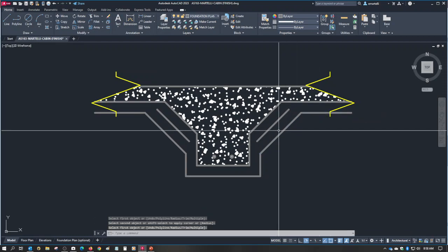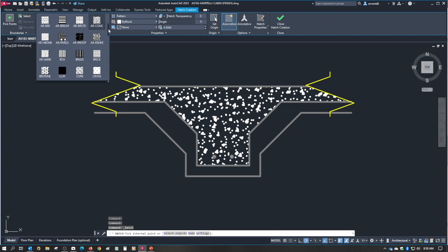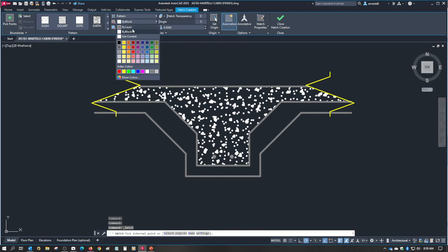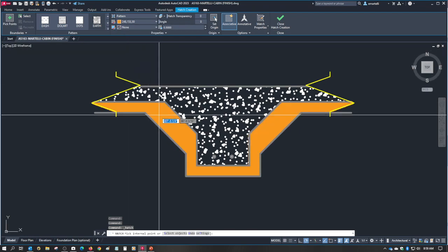And then use that earth hatch pattern. That might look pretty decent, I guess. Use earth hatch pattern. Watch. Earth. We're going to add earth. There it is. And if you want to choose an earthy kind of looking color, I guess that's fine, okay. You might have to play with the scale of it.